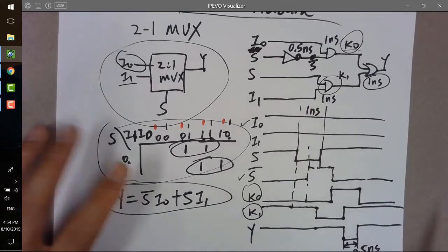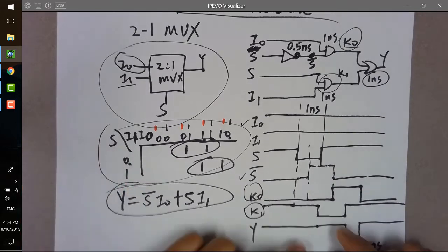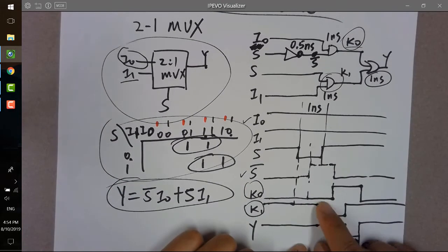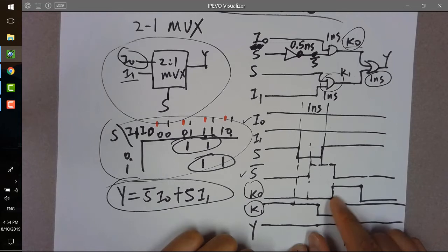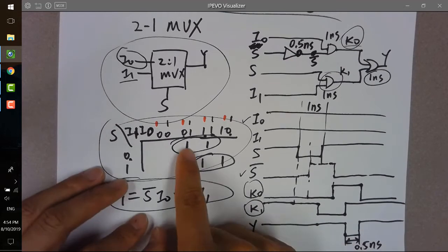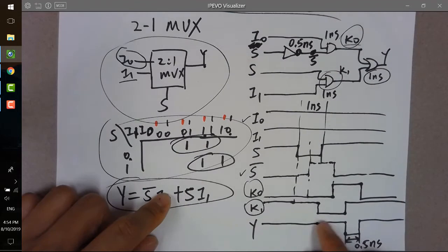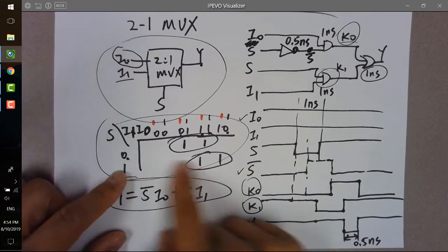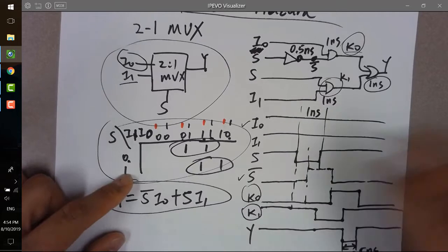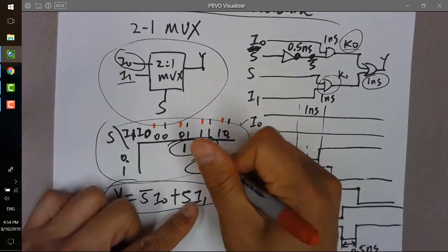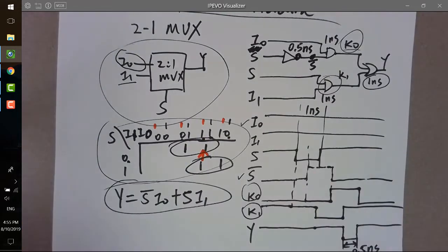However, the problem is, because of the time delay, you have a little bit of difference between these two signals. That's why it introduces a dip to here. However, you don't have that dip in the ideal case. So which means when the signal is being changed from 0 to 1, or 1 to 0, it jumped from here to here, and there's no 0 happening.